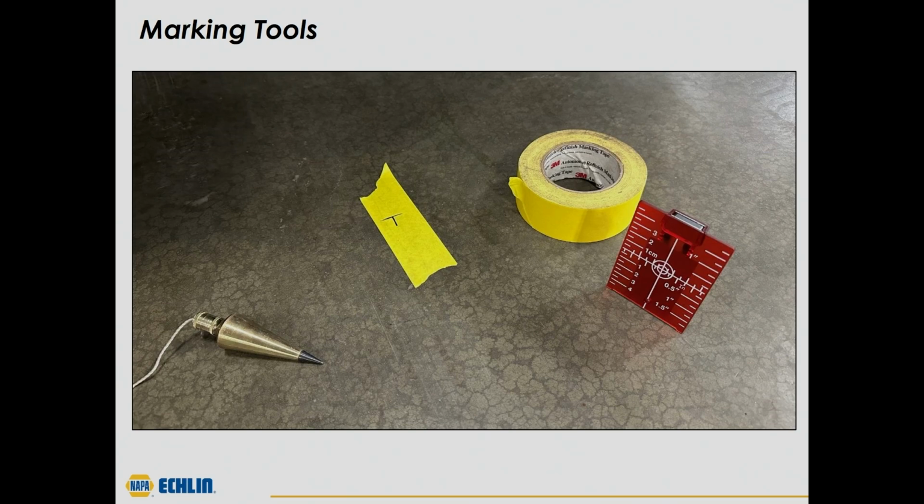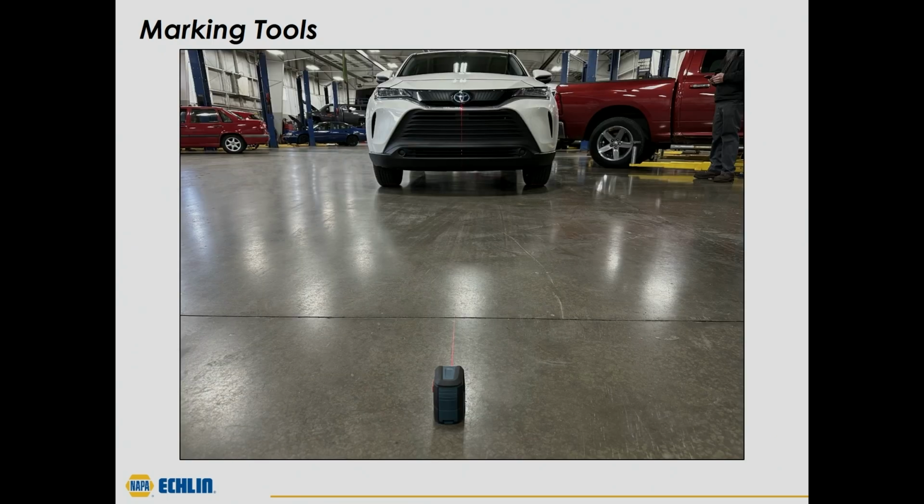We're going to place it at our mark, and now we can shoot our straight line, and we can then go and put our target where our measurement needs to be. So this is a very fast way of establishing our center line, rather than just taping down a string, throwing it under the vehicle, dragging it out, and then taping that down. If we've got a reflector and a laser, this can be a very fast process.